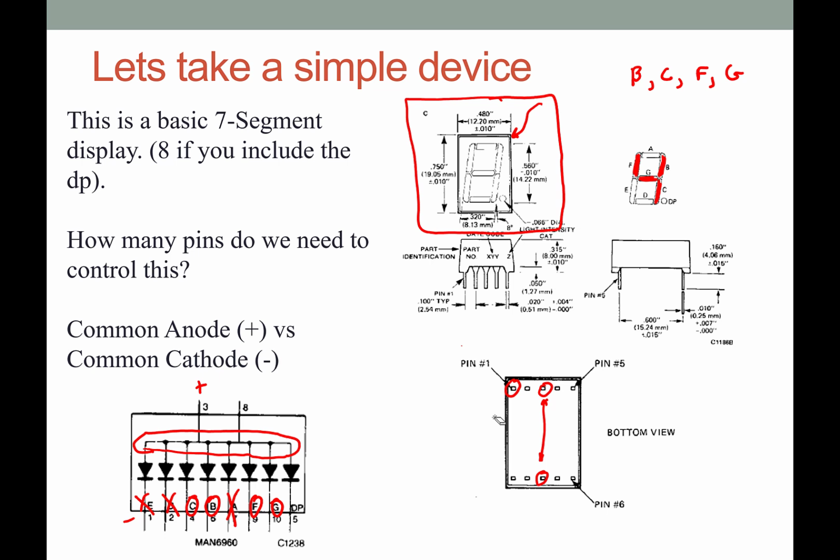Now we'll talk about that more as we get the pins for this to go, but let's just say we can somehow get VCC from the board, and let's just do this path right here because we said we wanted to light that segment. We can light this segment. Now we'll put a resistor on here, and what's the resistor for? Well, the resistor is there just to not have infinite current, and to limit how much can be supplied from this VCC source when we short the diode.